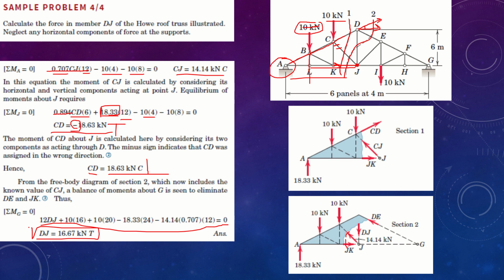The technique, as we have studied in both sections, is to choose a proper point of rotation. A good point of rotation is a point where the maximum number of forces have their effect reduced, minimized, or negated. In this particular example, we have chosen certain points like moment about point A, point J, and point G, to reduce the unknown forces as much as possible. As you know, the moment is generated by a moment arm, which is perpendicular to the force acting on that arm.